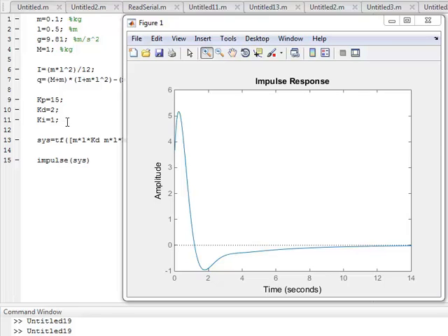However, in practice, much of the process of tuning gains is very similar to what we're doing here. We try different gains in a simulation until we find a response that looks good. Then we can go and use those gains in our physical controller and watch the actual response of the system. We modify the gains by small amounts until we find a response of the system that behaves well in practice.